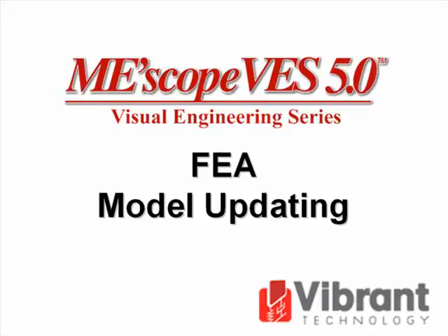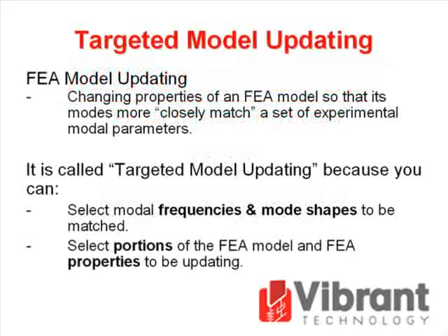FEA Model Updating. FEA Model Updating involves changing properties of an FEA model so that its modes more closely match a set of experimental modal parameters. It is called targeted model updating because you can select modal frequencies and mode shapes to be matched, and select portions of the FEA model and FEA properties to be updated.